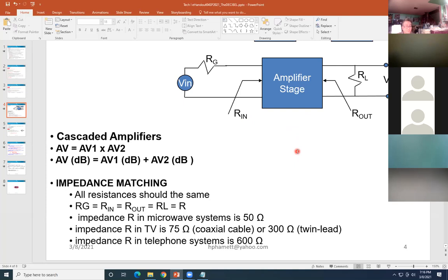Okay, thank you. There's a theorem about power transfer. When the load impedance equals the source impedance, or the complex conjugate of the source impedance, which we'll learn about later. But when the load resistance matches the source resistance, that's the maximum power transfer condition. And you can actually derive the equation, and we'll do that in our study group tomorrow.